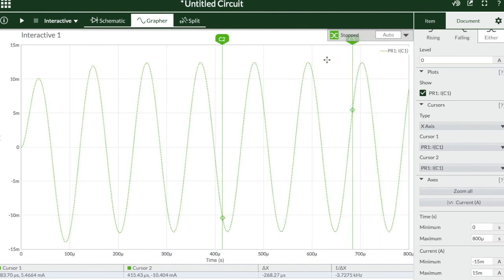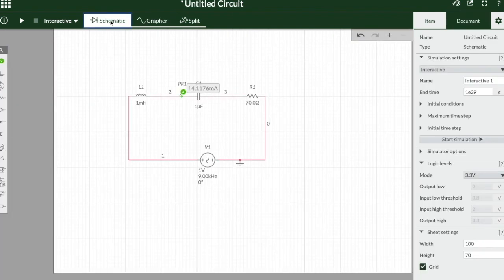So, to get a smooth resonance curve, we should take readings for various frequencies of the input signal over a range starting from below resonant frequency by 10 and increasing it through resonant frequency up to a value of frequency above 10 times resonant frequency. This is how we can study different aspects of LCR series circuit using the simulator Multisim. Thank you.